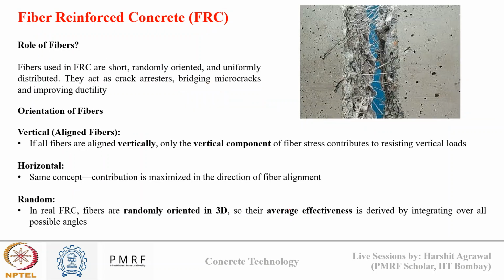Now, what is the role of fiber in fiber reinforced concrete? We can understand the same from this figure. The fibers that we use in FRC are short, randomly oriented, and uniformly distributed, and they act as crack arrestors, bridging the micro cracks and improving the ductility.